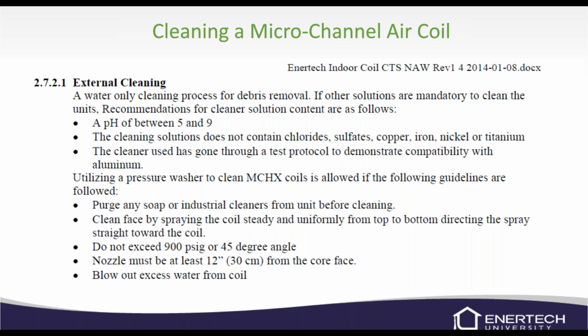Whatever you do, you can clean the face with a pressure washer, but you need to make sure you're always at a 45 degree angle and don't get too close. You don't want to exceed 900 PSI. I wouldn't even come anywhere close to that, and stay at least 12 inches away. That causes us not to be able to clean the coil in place. If it gets so dirty that it becomes a problem, you're probably going to have to remove the refrigerant, pull the coil out of the unit, and take it outside and clean it.